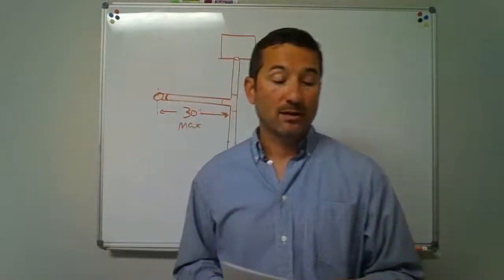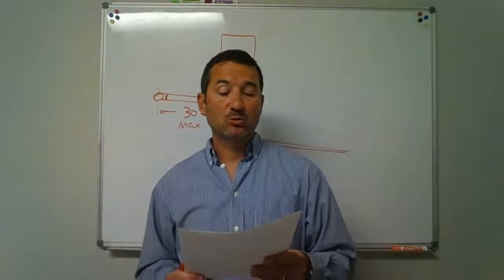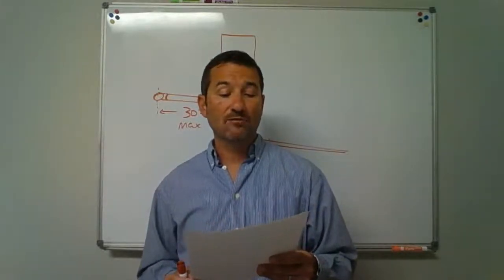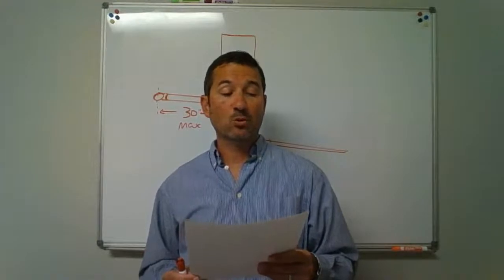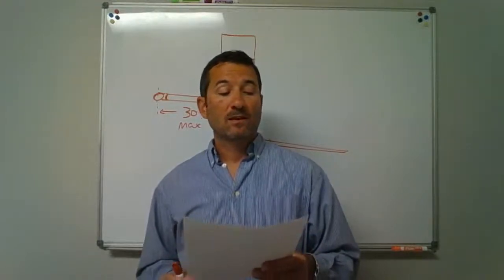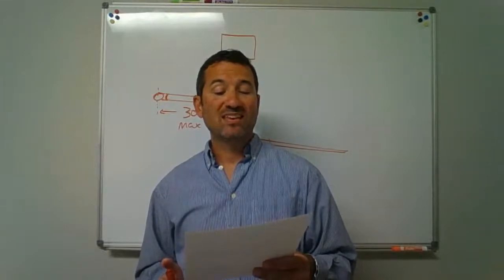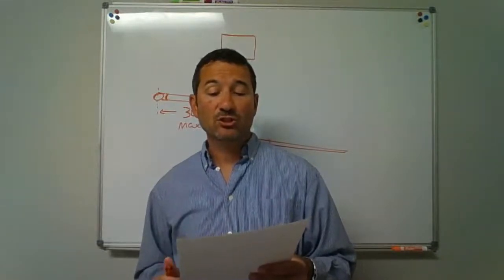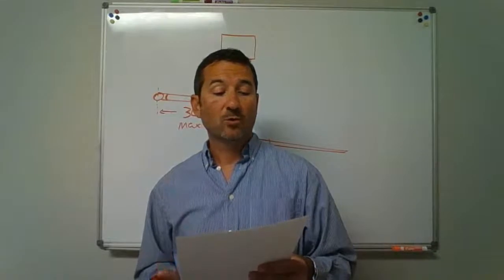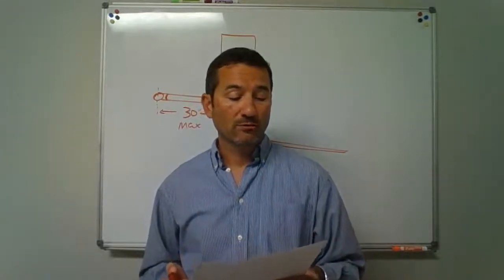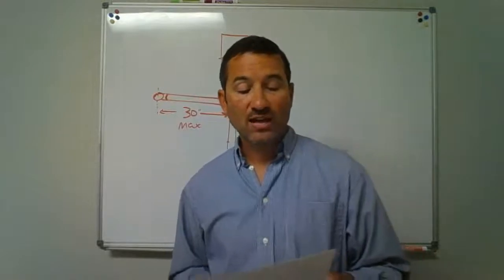Question 7. An air brake shall be provided between the indirect waste pipe and the trap seal of the waste receptor or standpipe. True or false? Question 8.